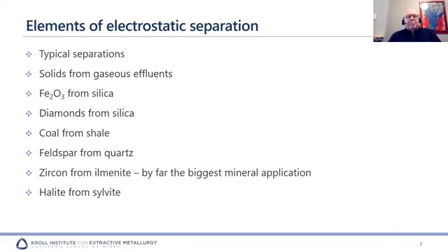And there's many examples, like pulling out Fe2O3 or hematite, hematitic iron from silica, diamonds, cleaning up coal, feldspar. But by far the biggest one is the separation of zircon from ilmenite out of a heavy mineral beach sand operation. These are alluvial type operations, and this is the biggest application.